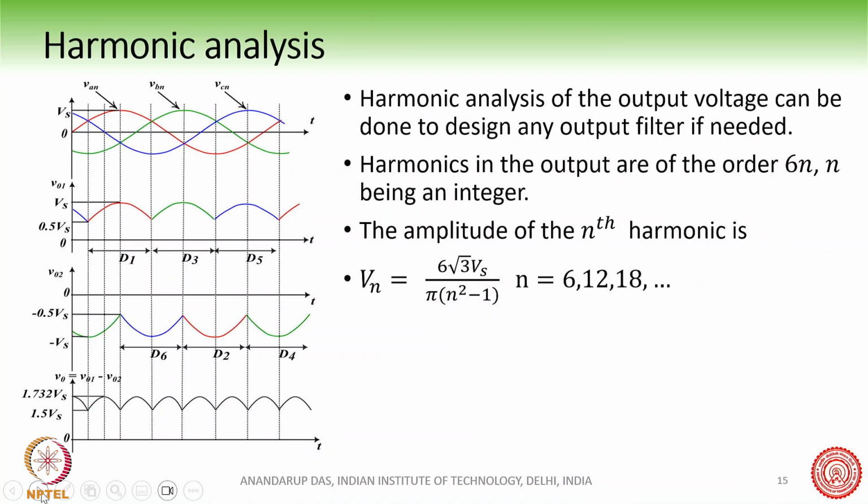One thing that is also important to note, but we will not discuss in detail, is that harmonic analysis of the output voltage can be done to design an output filter. If you do the harmonic analysis of this waveform, the amplitude of the nth harmonic will be Vn equal to this value. You can do it yourself.